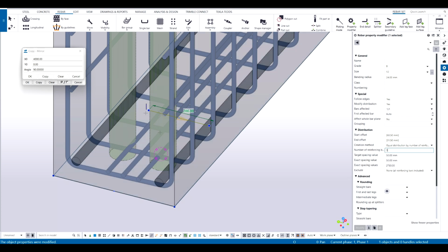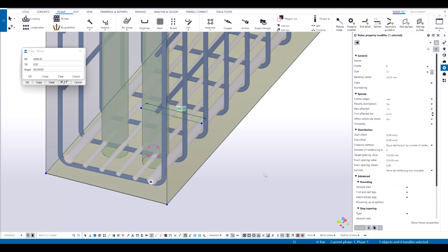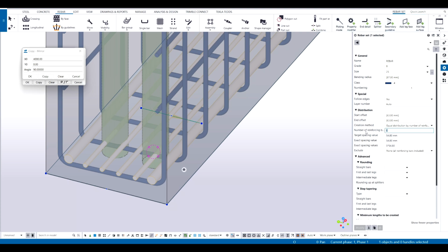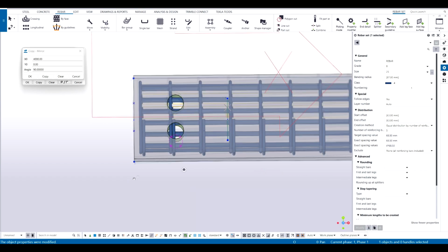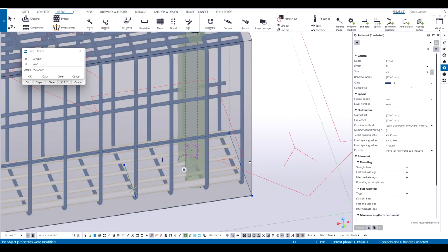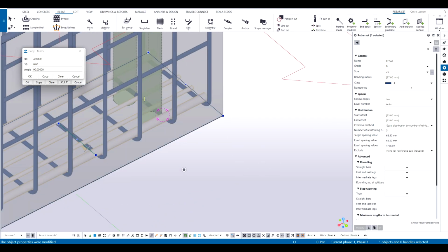This also does the thing, but if you look at it, it's doing some spacing problem. So I'll edit that from the main parent thing. So I go here again and I'll make it as 5 here so that the spacings are adjusted. I did that for a reason. I just wanted to demonstrate how easy it is to stop this path before the grout tube. At the moment it looks like it's clashing with my grout tube.